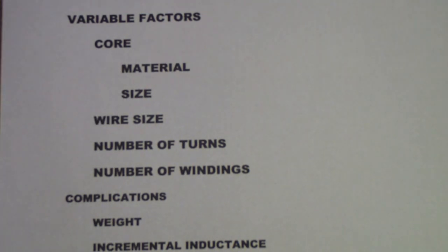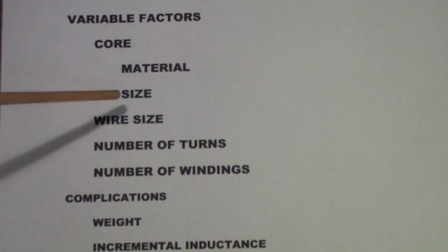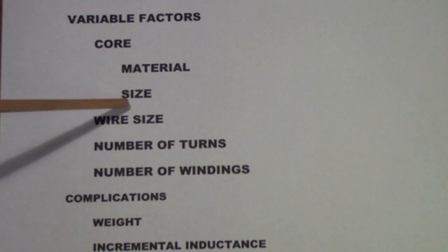The problem is that the transformer very soon becomes so heavy that the amplifier is basically immobile. In fact, to really achieve a good 10 hertz to 100 kilohertz tube amplifier using core material alone and no special tricks with windings and other things, you need about 100 to 150 pounds of core material.